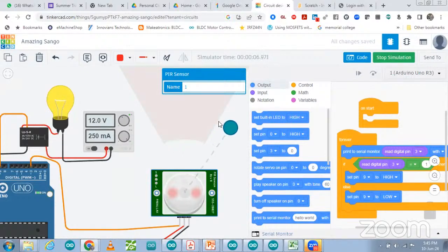In replacement of the bulb, you can add any other thing that you want to turn on using this. You can make a theft alarm, or a buzzer, as we discussed earlier. So the relay is a very important component. With its help you can make many projects very easily, and a relay costs approximately 90 to 100 rupees, available in the market. You can easily purchase it, mount it with the Arduino and connect any kind of AC load. But you should know how to use a relay, how it works, and what is inside it. We have discussed all these things here.